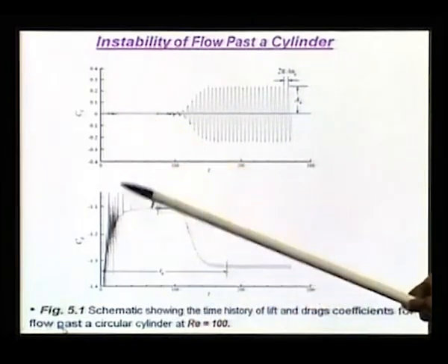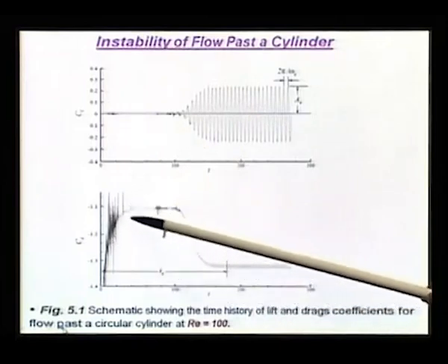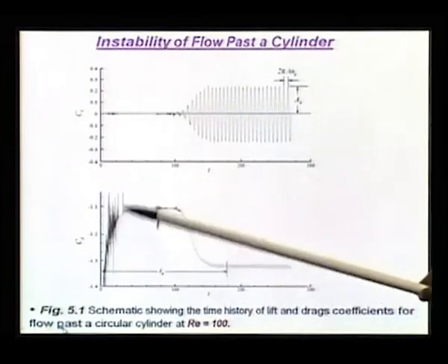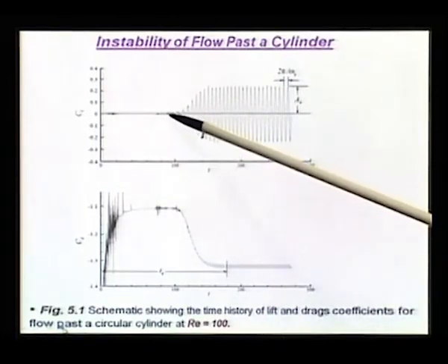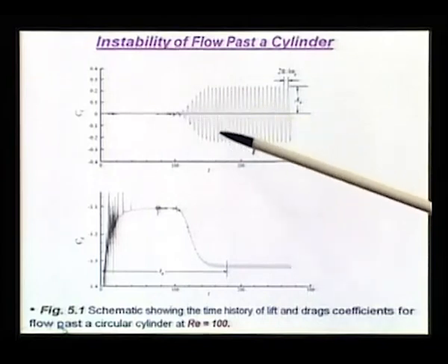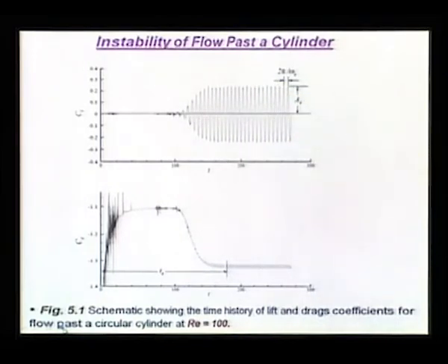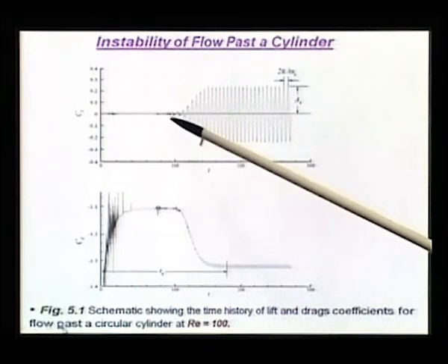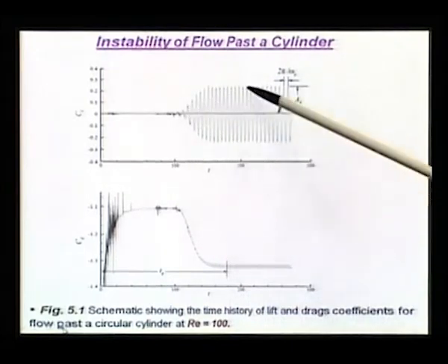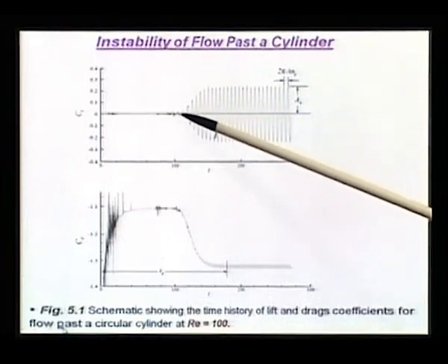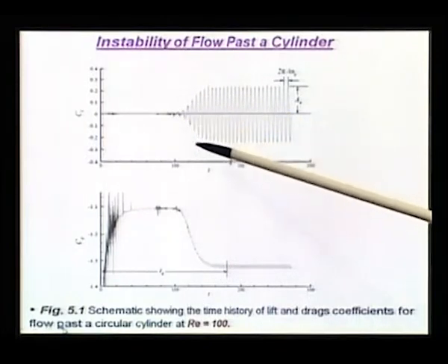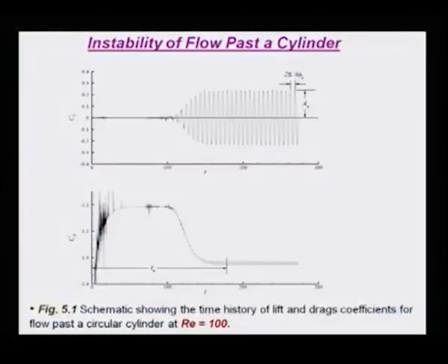Those fluctuations are present there too. Despite those high frequency fluctuations, the flow remains insensitive. After some time, slowly you start seeing the instability predicted by linear theory picking up. This initial exponential growth is governed by the linear instability, and the nonlinear saturation is quite nicely modeled by the Landau equation.